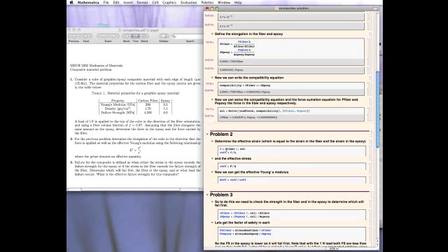The elongation is the same for the fiber and for the epoxy. They're equal. And so I'm just defining delta as the elongation. Here I'm setting it equal to the fiber's; you could do it with delta epoxy and you get the same answer. I have to do this little trick here, this little bizarre Mathematica notation that means take the results in the solution, this solution from the Solve, and put it into this variable.